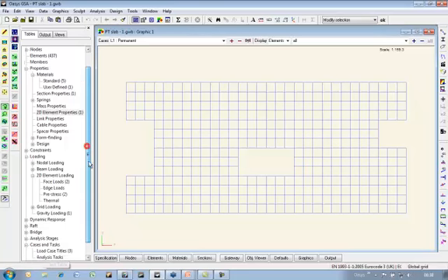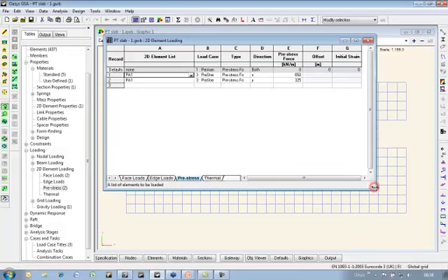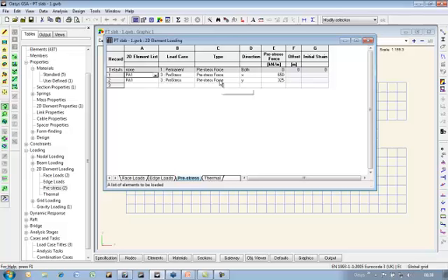But we also have a pre-stress value on the slab. For simplicity, I've just taken a straight axial pre-stress force. Reality is obviously tendons are moving around, but for the footfall, in this case, I think we can just take the overall force on this.